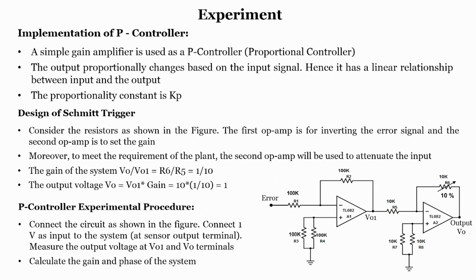That is the reason we are using 2 operational amplifiers to have the same phase, and a feedback resistor with a lower resistance value compared to the R5 resistor in this case, so that rather than using it as an amplifier, we can use it as an attenuator. But the factor entirely depends upon the resistance value that you choose in the feedback, which is nothing but R6. So one thing is clear: the gain is 1 by 10, that we have already seen, and the system has the same phase with respect to the input.